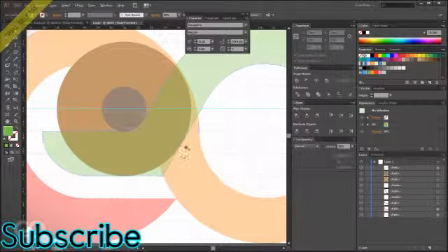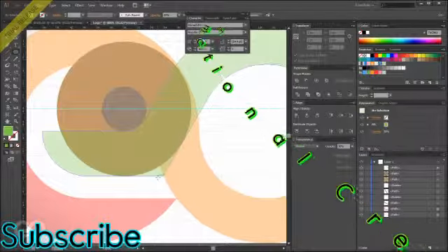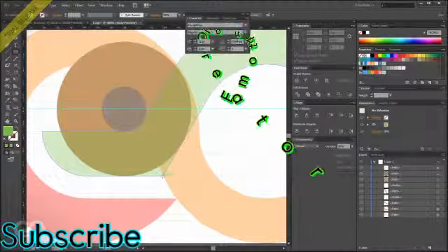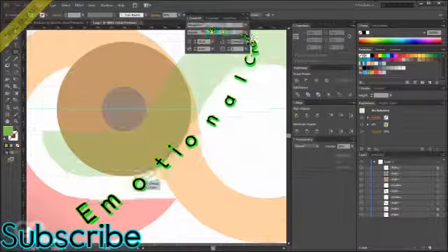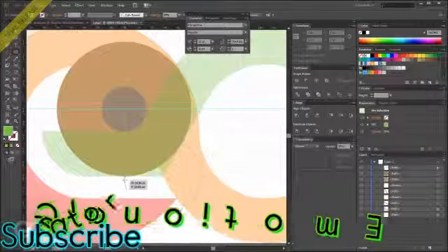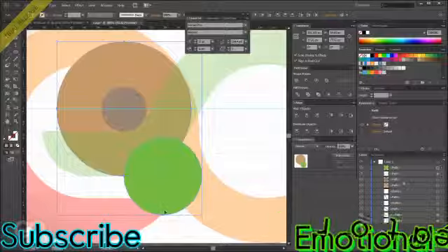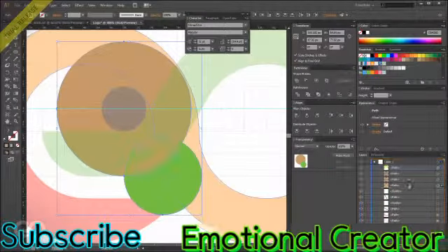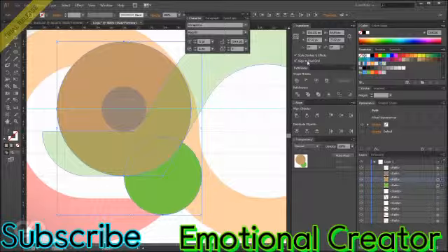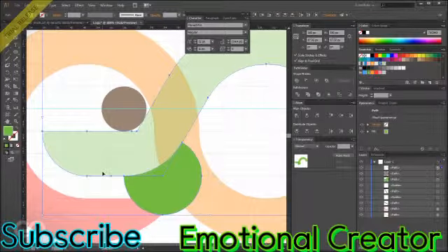Now, to create this smoothness, what I'm going to do is I'm going to create another circle which is going to start exactly from this point, the corner point of this. And this circle is basically going to extend exactly till the intersection point or the anchor point here. Now the reason I've created this way is now if I cut these off together, trim them, you can see it creates this circle which is exactly starting and stopping where the smoothness is supposed to be.